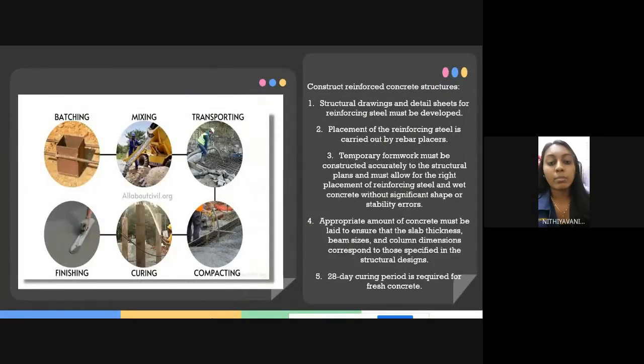This is the manufacturing process of concrete. First, batching. Measure the concrete mix ingredients by either mass or volume batch accurately. Next, mixing. Mix concrete ingredients by hand or machine mixing and should make mass homogeneous, color coordinated and consistent. Then transport concrete from mixing plant to construction site as quickly as possible. Next, place the concrete within 30 minutes of adding water.